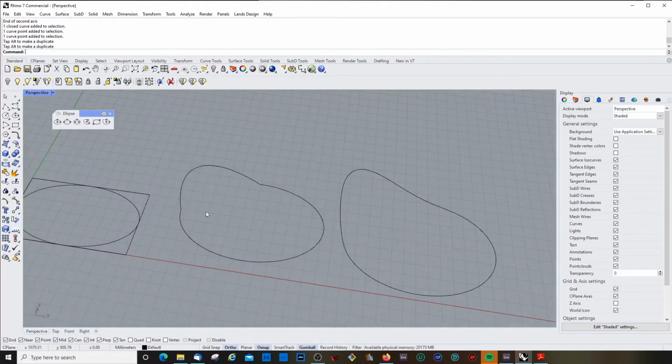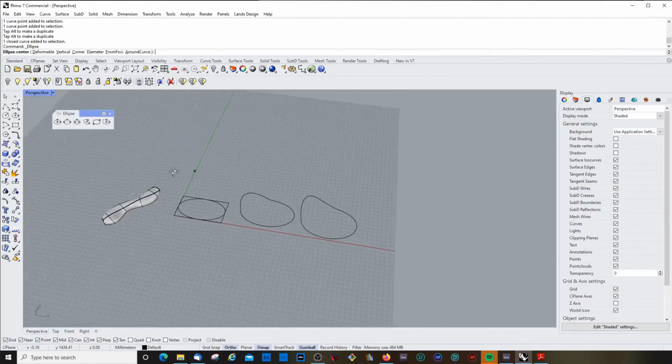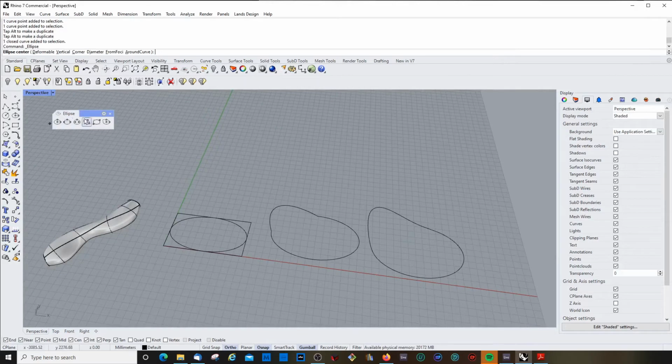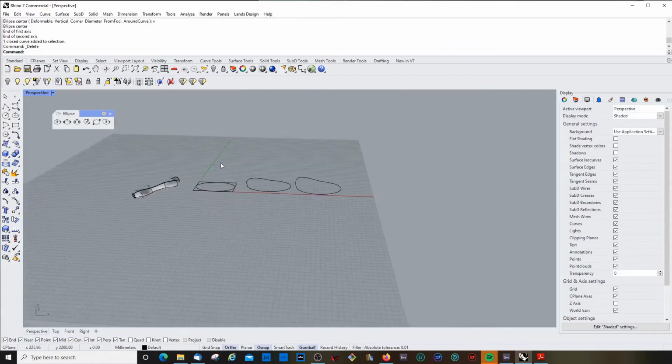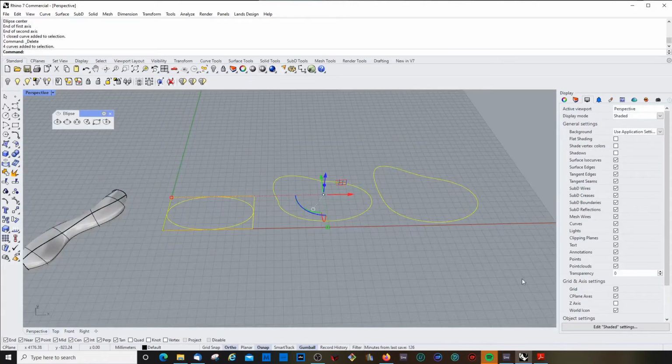Yeah, makes a big difference. And one more thing, which is actually not in here, that's interesting. It's the vertical one. We talked about this before. Actually, there's no button to click for vertical ellipse, but you can just type V, enter, and then it's gonna be a vertical ellipse, like the circle. Okay, let's kill that.